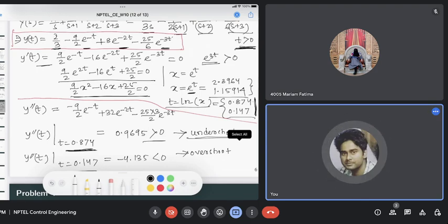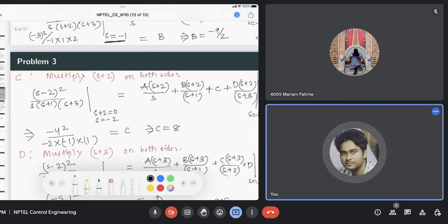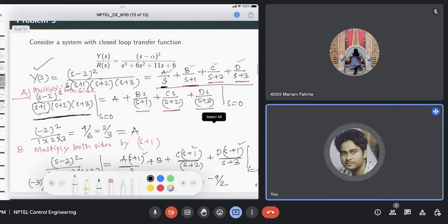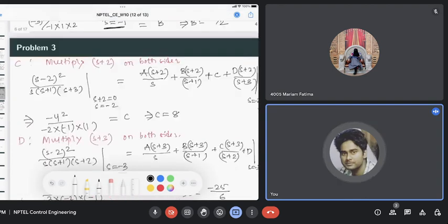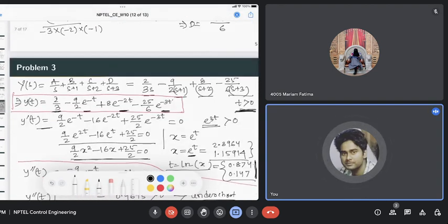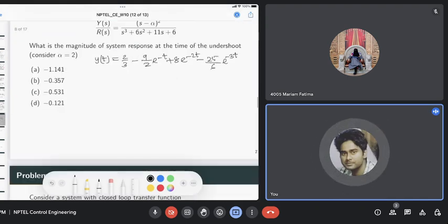Only the coefficients will be determined by the zeros, and the term that is present in the numerator, as you can see here. So this term will determine the coefficient values A, B, C, D. That's how we computed. The other terms determine the transient response, like this pole. That is also evident from this response, right? Because of the presence of the pole, we will have these kinds of terms. Where the pole is located, we will have the exponential term, and if it is a complex conjugate, then we will have sine or cosine terms, right? So for this real part, we will have this response.